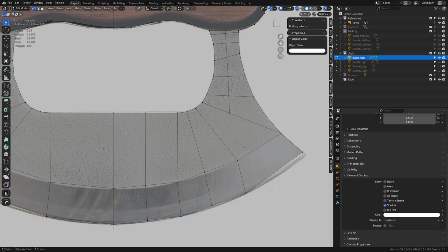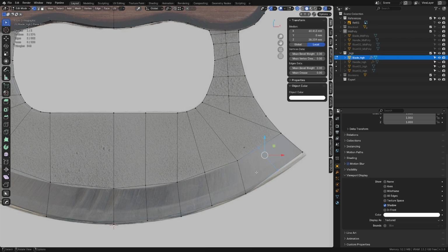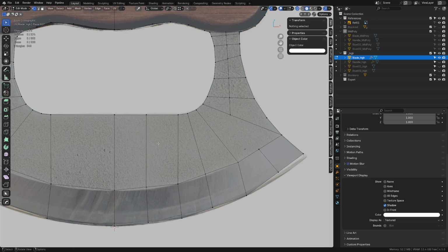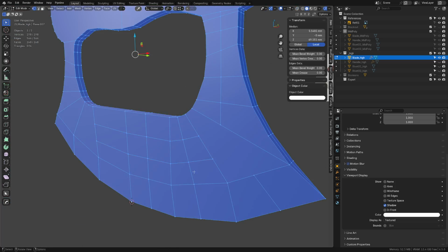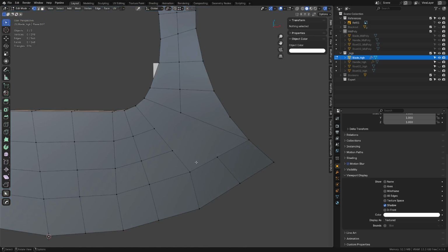And you can see like we're missing the curve here. This is why I'm prepping for this area basically. Like if this is going to get cut at some point, we're going to shift all that around, and we're going to realign all this basically. We don't want big rectangles necessarily. Oh, we could even get away with like 2 loop cuts in here, perhaps, right? Something like that. And you can see I did it to the backside, and I'll try to work on the backside. So yeah, be careful with that too.